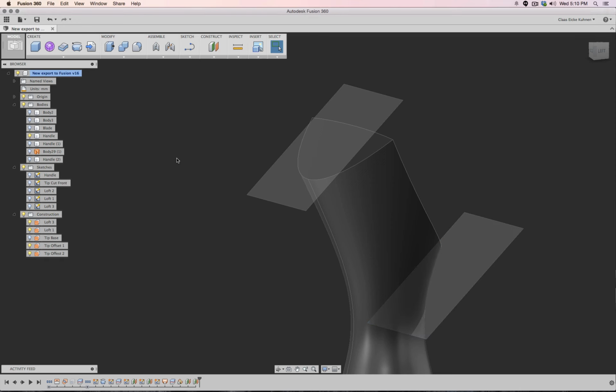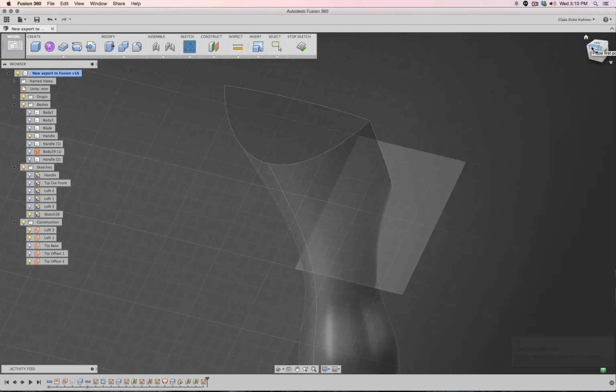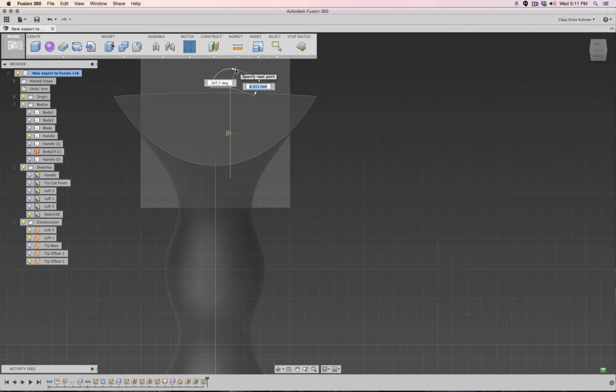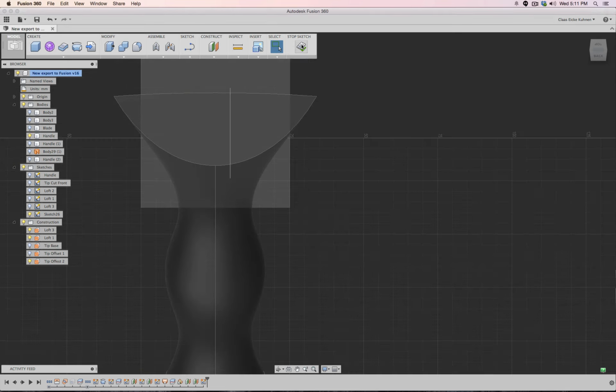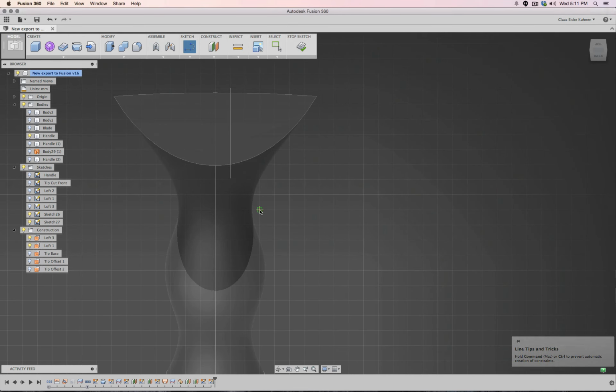Okay, so now on those sketch planes, I basically start creating those lines again. So create a line on here, go into this view, say maybe from there to there. So here I would like to have maybe a linear part. Okay, I'm going to delete this part, and actually, because my blade is horizontal, I keep it that way. Good. And then another sketch here, maybe there to there.